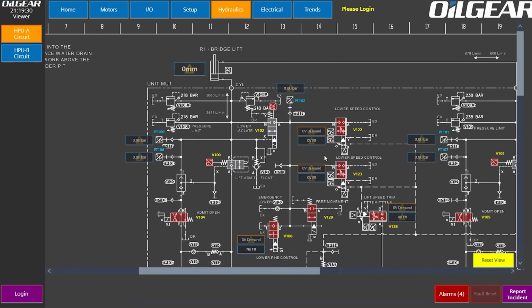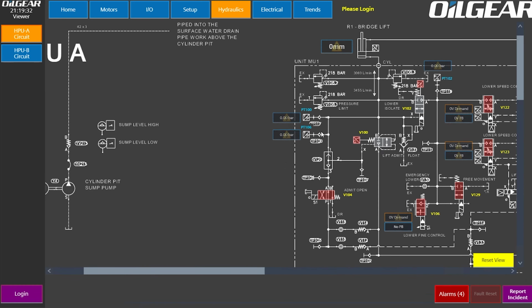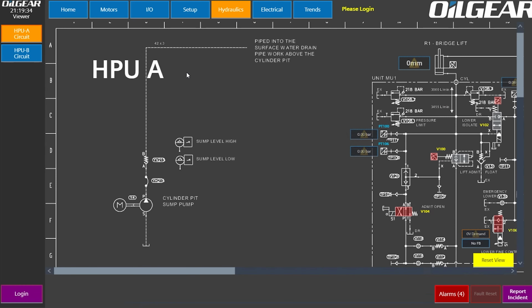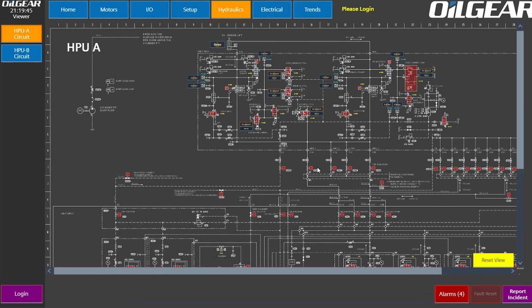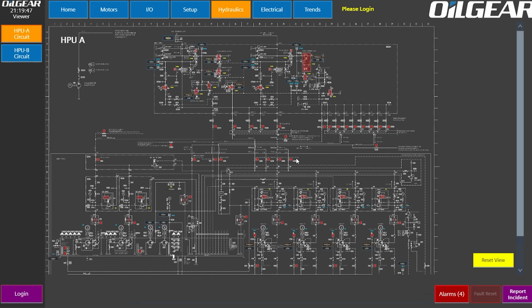So my process is this, and what you're looking at is WinCC Unified, but what I'm saying is not specific to WinCC Unified at all. You could use it on any HMI software. Essentially, I get a PDF version of the hydraulic circuit, and I then convert that to an image, a PNG image.